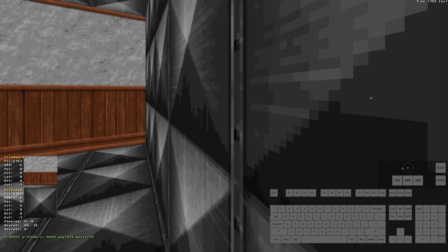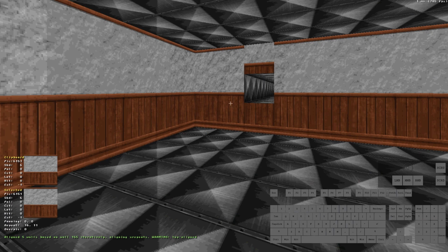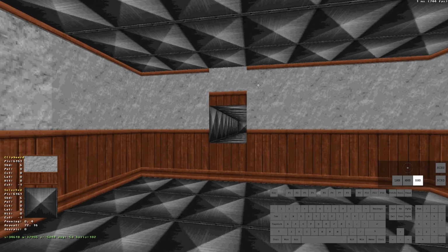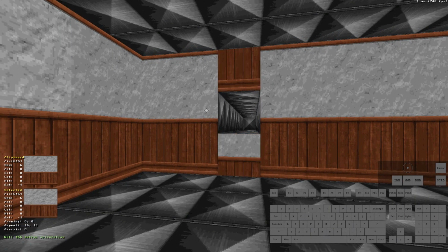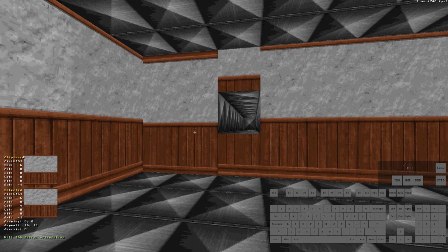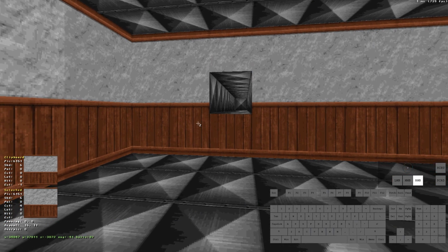If we try to align adjacent walls when there's a division like the one from the vent, we have to press the O key first on a normal wall, and then press the dot or comma key. So all adjacent walls will align and also change their orientation.